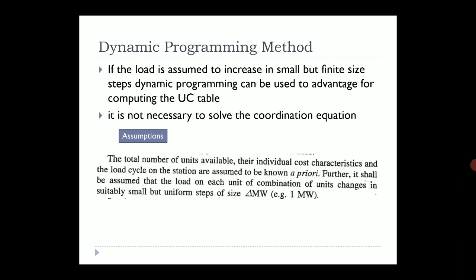Okay, so is it a bad assumption? No, because in our general cases the load changes very slowly. But if the load changes very fast, then some other method is used. So unit commitment is applicable from the morning to the evening period, when the amount of power is required. But from the evening to night there will be a sharp fall in the load. So you cannot apply unit commitment or the dynamic programming method there.